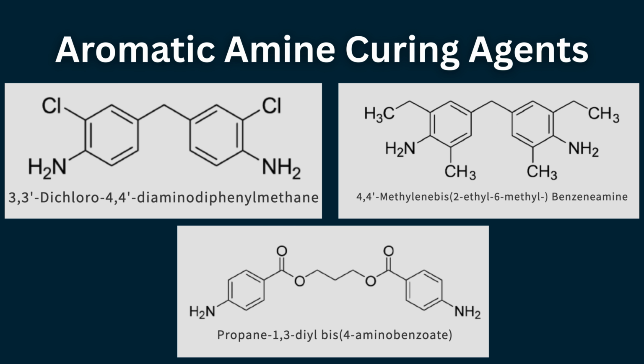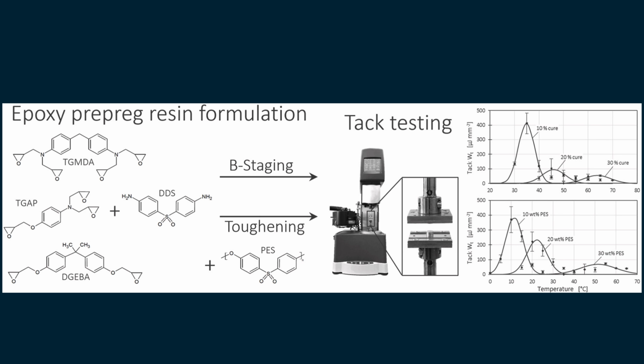Another limitation is the dark color of many aromatic amines, which can stain skin, equipment, and substrates during processing. Furthermore, the cured epoxy networks produced with aromatic amines are often relatively brittle. Nevertheless, the relatively low reactivity of aromatic amines can be advantageous in some adhesive systems.